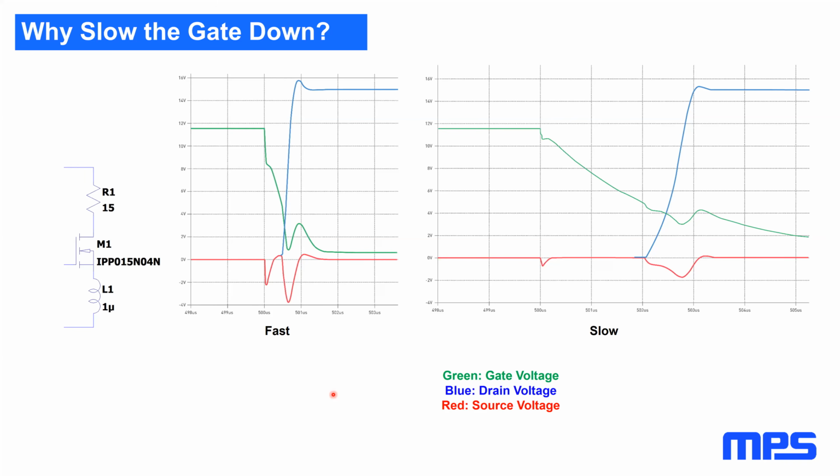And then MOSFET gate drivers are available in a vast range, like 100 milliamps to a few amps. Is there any disadvantage to using higher current sink source gate drivers? So the first thing you need to do is figure out how much current you need. And that's a function of the MOSFET, its gate charge or gate capacitance, and how fast you need to switch.